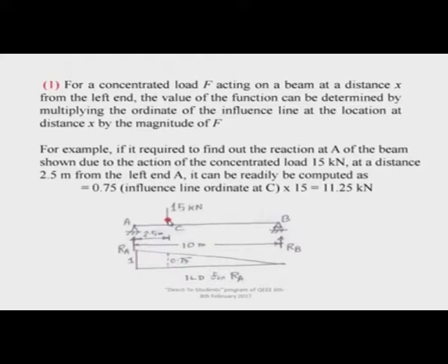Please once again see this influence line diagram. Once the load is here, I am always sitting here. So, when the 15 kilonewton load is here, I will face the full 15 kilonewton load on me, and I will say that the reaction is 15. You may say that this is plain statics, it is on the support.